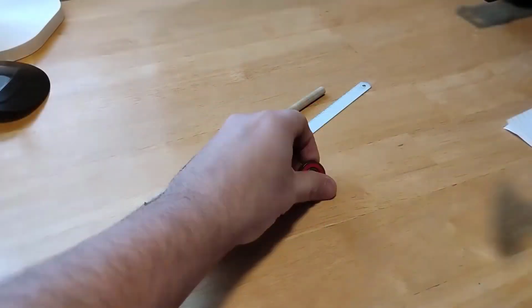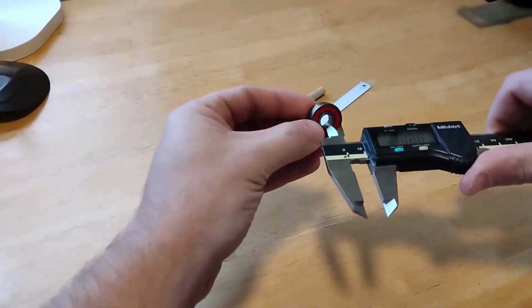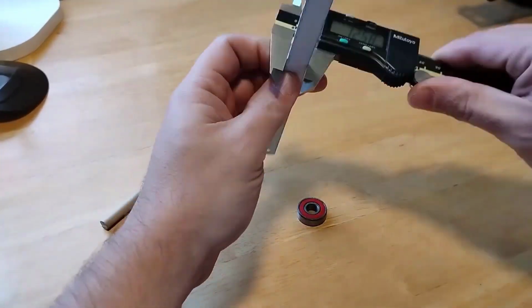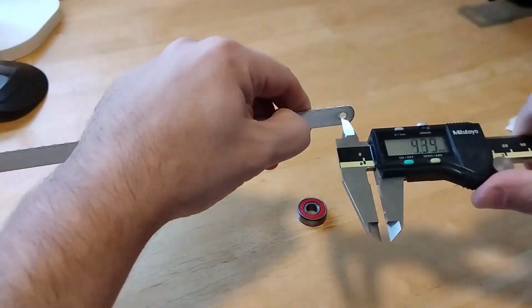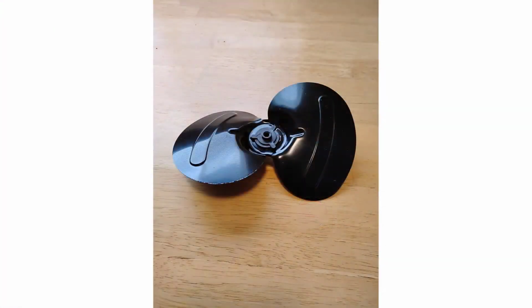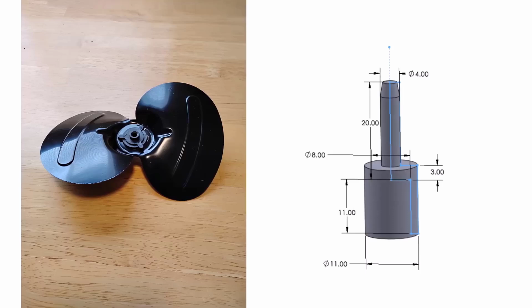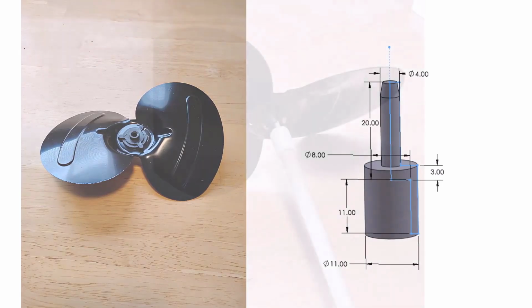Be sure to have your purchased components in hand before finalizing your design. We want to take accurate measurements of the fan, bearings, and dowels to make sure our printed parts fit properly. For my design, I took apart an old space heater for the fan blade. The shaft diameter was smaller than the 5/16 dowel I was using, so I drew up and 3D printed an adapter.